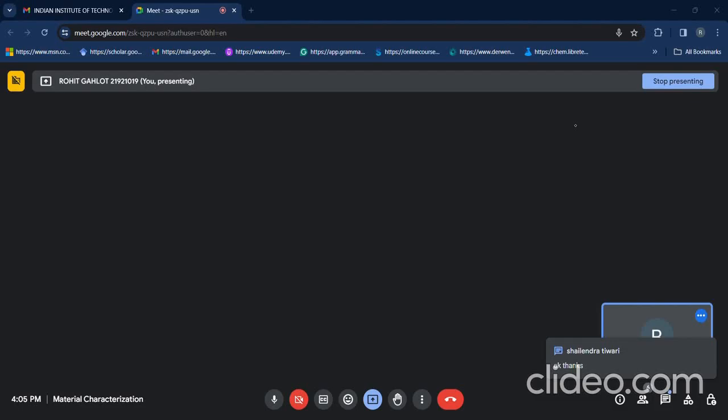Similarly, for powder samples the voltage is generally less than 10 kV. However, for metallic samples the applied voltage is around 20 kV. The reason has already been covered in the lectures; this is just a briefing. For the TEM part, I will discuss it when TEM is covered, so I'm leaving this. Besides this, there are the scan coils, then the aperture, and then your specimen.